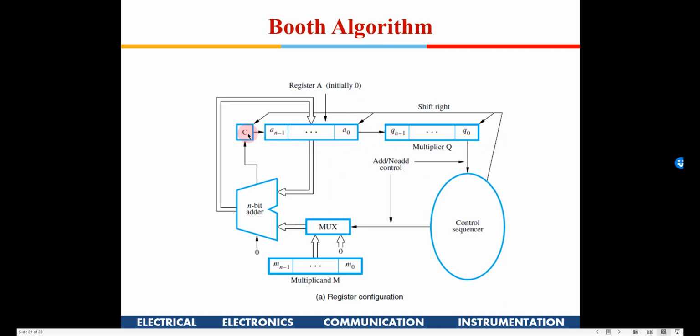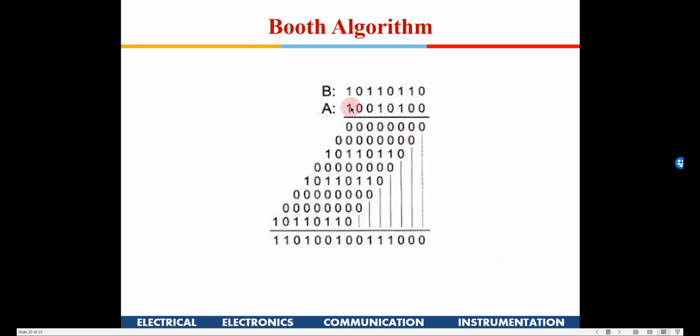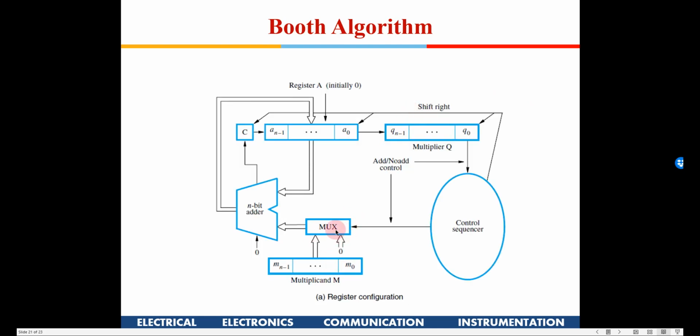So I am using a shift register to shift the data towards the right, okay. It is serving two purposes. One, it is shifting, also it is pushing out the A data. So initially we have pushed A into this, right. Every time you are pushing out, this will go automatically. We are looking at the last digit out here to decide this control signal, right.